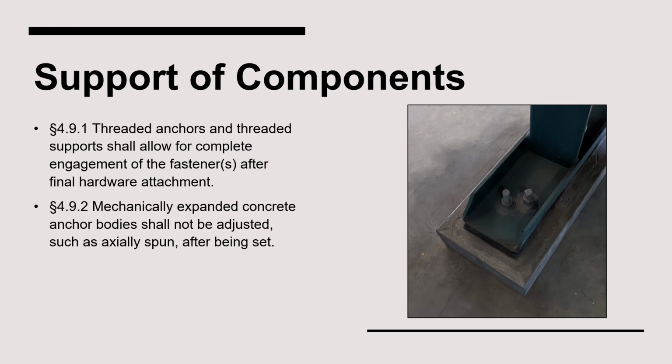As it relates to supporting and anchoring a compressor, any threaded fasteners must be completely engaged. The nut on the right is an example that is fully engaged. Additionally, expanded concrete anchors must not be spun after they have been set in concrete.